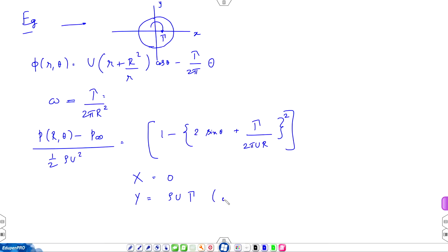Okay. So, let us write down on the cylinder. So, now the lift is no longer 0. Y is the force acting in the y direction, which is at right angles to the flow direction. Therefore, capital Y is also the lift experienced by the cylinder. So, this result, it is a non-zero value, does it match experiments? To a great extent, yes.